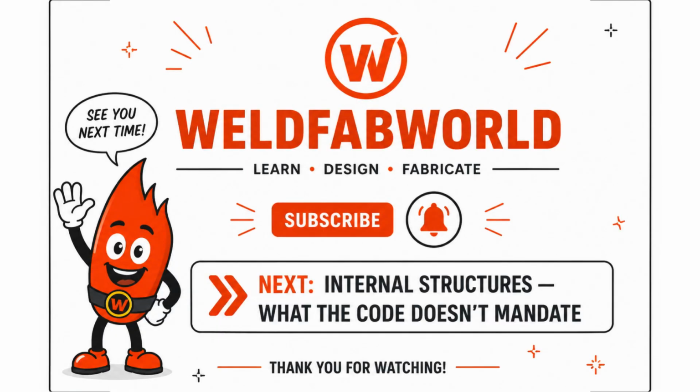Quick recap: Part UHX governs shell and tube heat exchangers, but tube sheet design itself is now entirely Division 2, Part 4.18, invoked through Mandatory Appendix 46 from Episode 1. Everything except the tube sheet stays standard Division 1, and the nameplate has to separately mark both the shell side and tube side. That's Season 3, Episode 8.